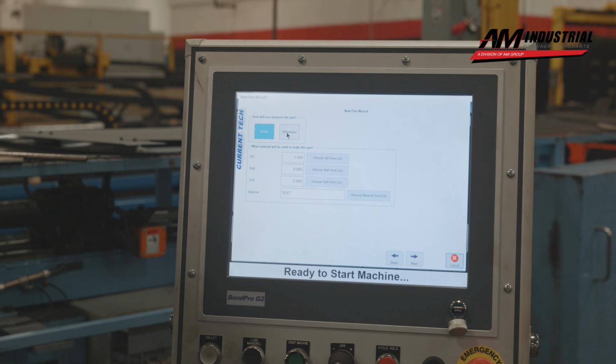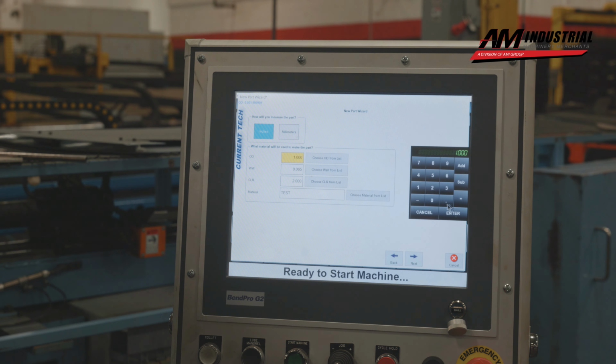You can talk in inches or millimeters. We're going to talk inches today. We're going to change this to 0.375 because that's really what we have for an OD of your workpiece. Then we have a wall of 0.065. We have a center line radius of 2.